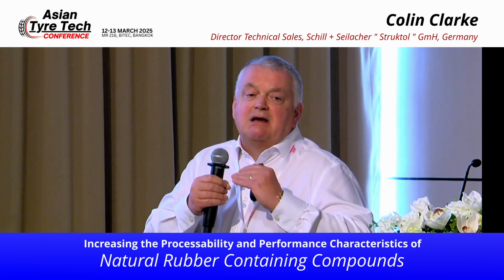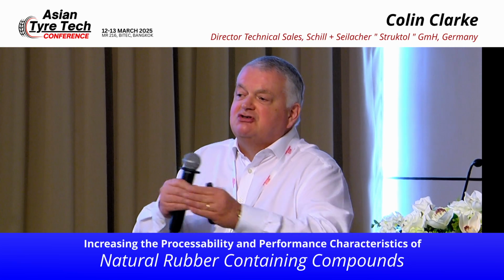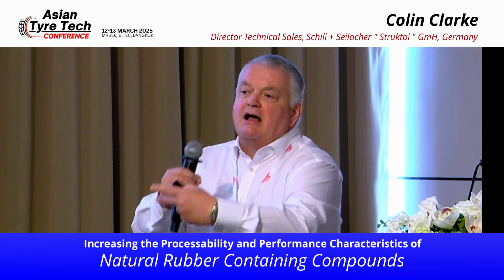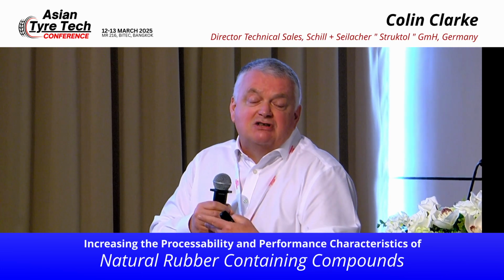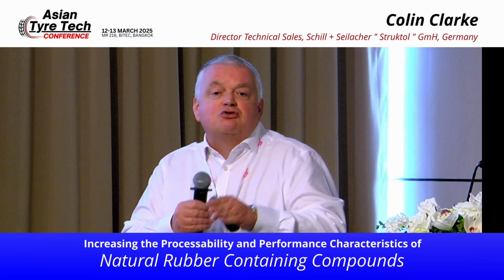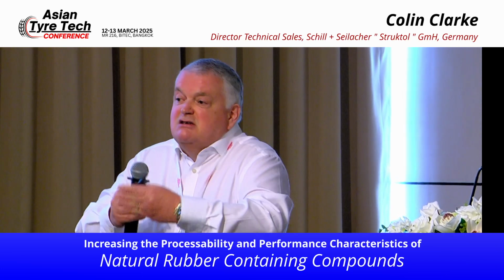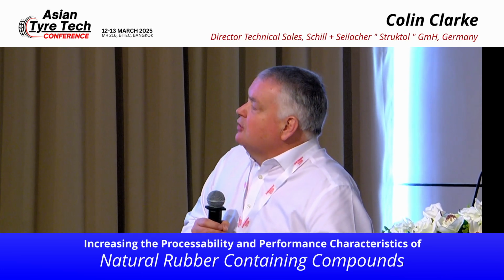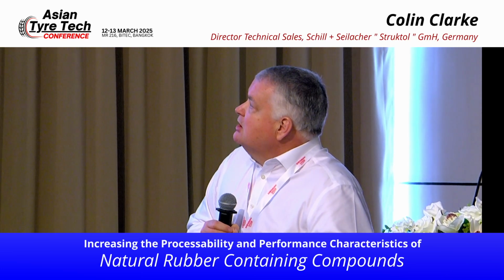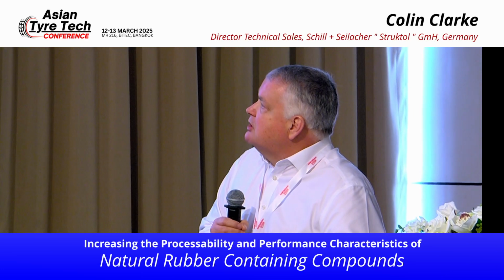It's also much less temperature sensitive, so variations in temperature as you start with a half-filled mixer, you add your carbon black and ingredients later in the same stage, the temperature variation is greater, but the new peptizer is much more tolerant of that as a chemical change, if you like, than you would have with a conventional chemical peptizer. So let's take a look at how these products work.